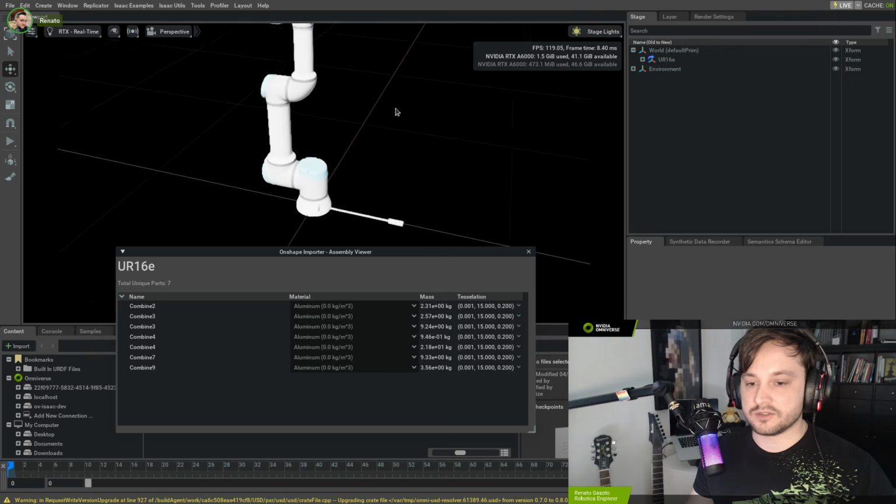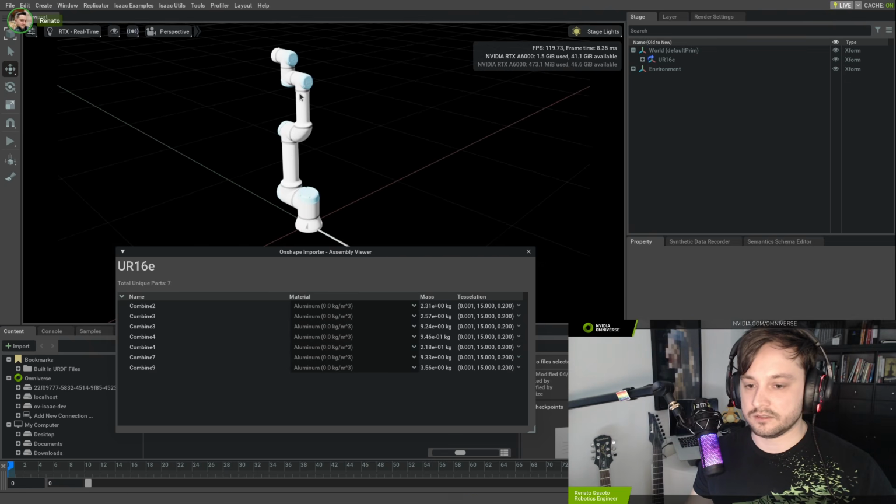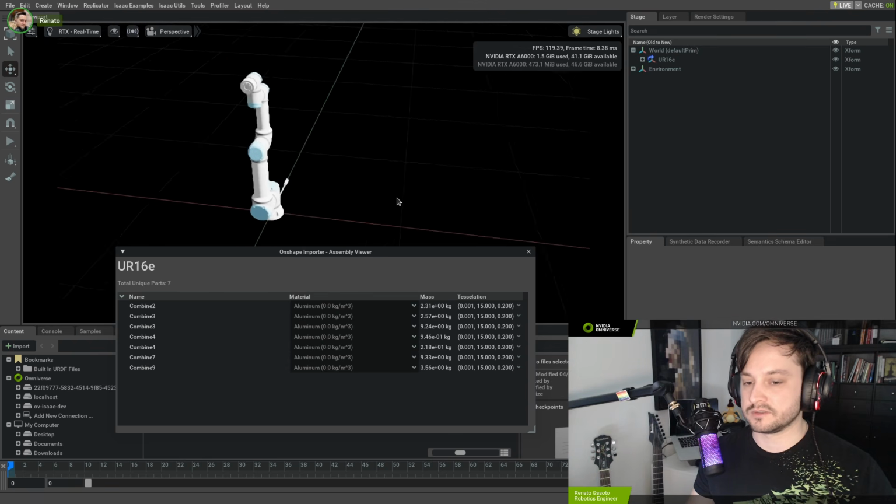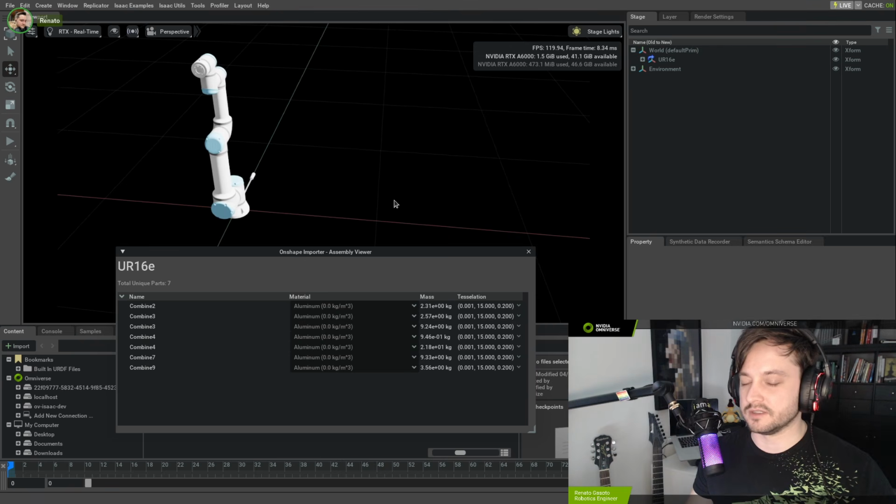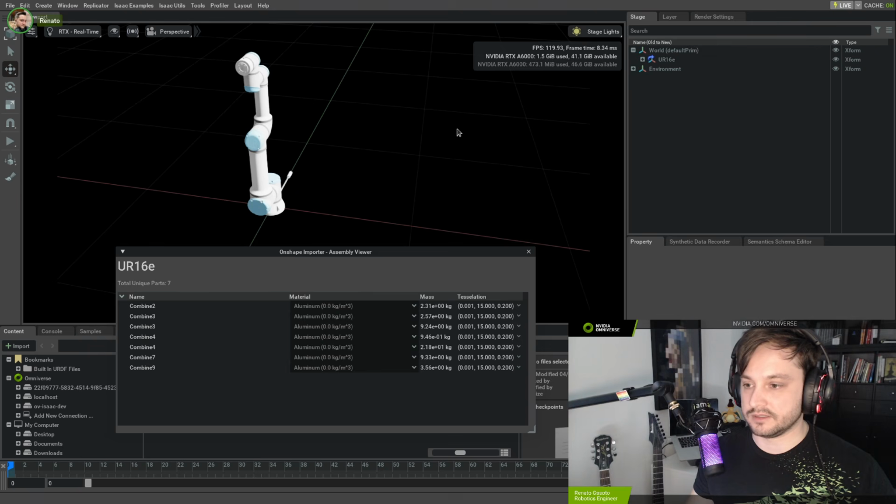And one thing you can notice here, because the CAD file was with the robot pointing up, this is the default pose that it comes in for us. If we needed to change that, because as I remember, the URDF comes with the robot actually tilted 90 degrees, we can change that directly on OnShape before importing, and it would assume that is the base pose. It doesn't change the limits. The limits will apply as if that is the base pose. Just for clarification on how the importer works, and this is based on the OnShape API.